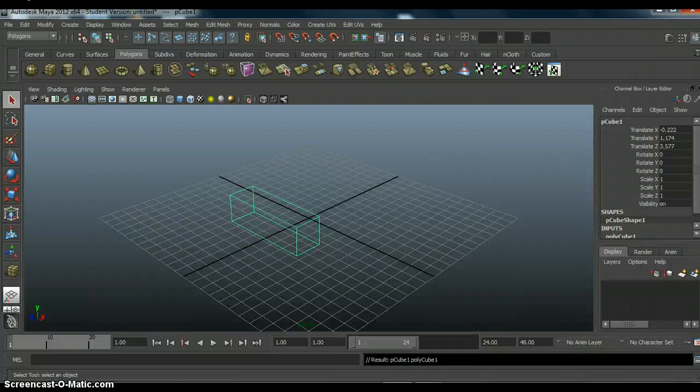It is currently in wireframe mode, so I will switch it over to the shader mode. That way we can see all the faces and the wireframe around it. Okay, over on the right side, the attribute editor has been filled with numerical values that stand for the position of the polygon on the grid and also its scale and size.